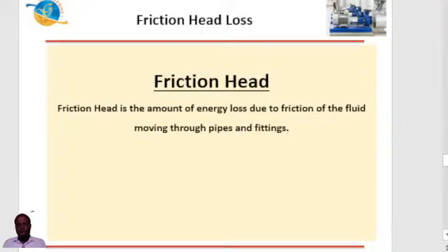Because if you don't take account of your frictional head loss when calculating the total head requirement, and you install that pump, then by the time the pump is put into operation and friction starts manifesting in the pump, the total head capability of the pump will go down.